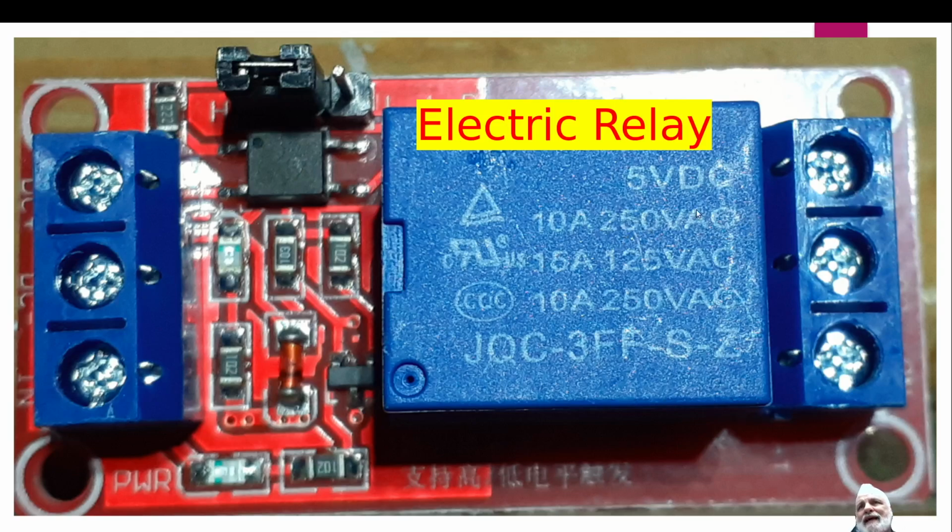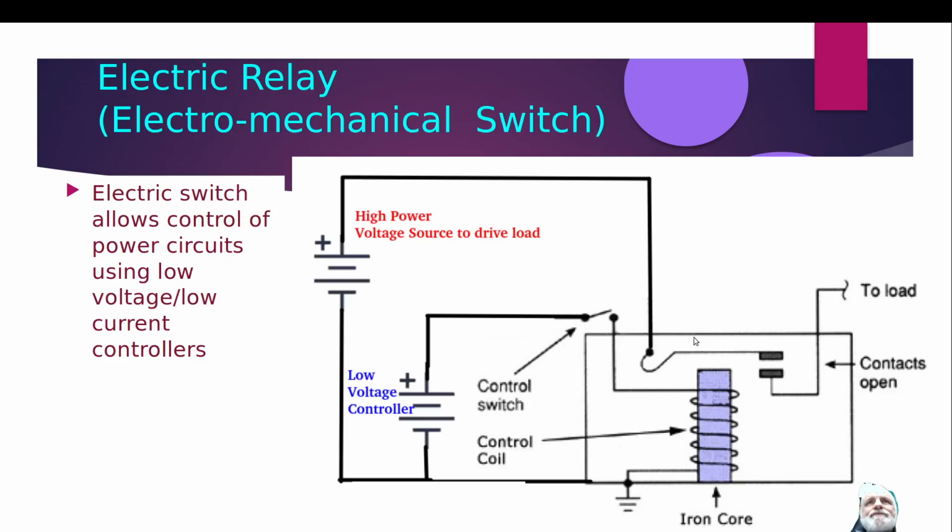Okay, so we can activate this relay with the 3.3 volts from our Beaglebone. It says 5 volts, but 3.3 is enough to activate it. And that'll activate this relay, and then you can literally power like a light or even a small heater or something along those lines. So the way the relay works is it allows you to activate it with a low voltage, and then you can drive a much higher load with much more current and much more voltage.